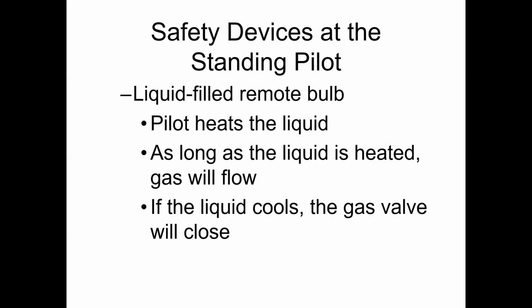For a thermocouple, the soot buildup is going to stop the transfer of electricity. For the soot buildup on a liquid-filled remote bulb, it's going to stop the transfer of heat, preventing that liquid from expanding and moving that diaphragm. That's what can happen a lot of times.